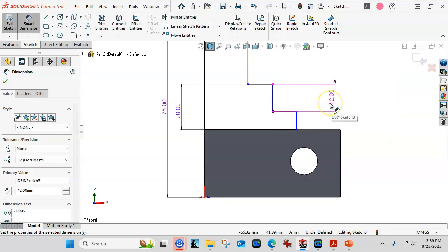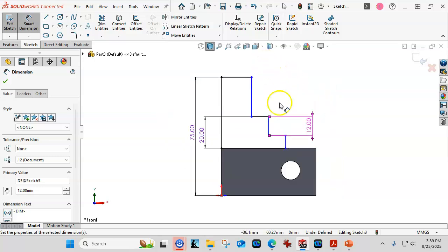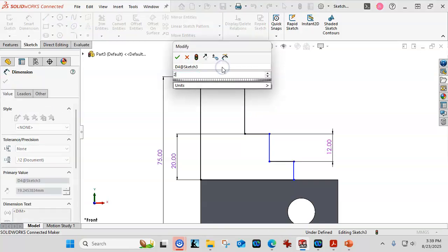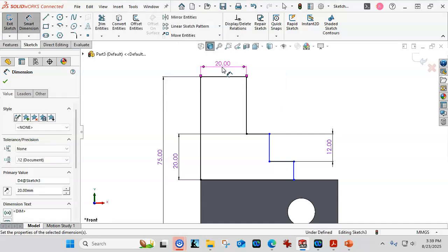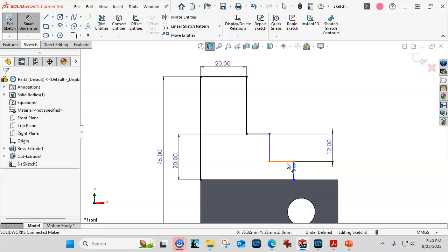dimensions. All right, and then so we had the 20, we have the 12. I'm using the scroll wheel to zoom around a little bit, and we'll go to the top, select the object, place the dimension, and enter the value. All right, and then our next, even though it's kind of rotated there. All right, so there I selected a midpoint. It jumped right out at me and I got it. All right, so I need to hit the escape button to get out of the midpoint.